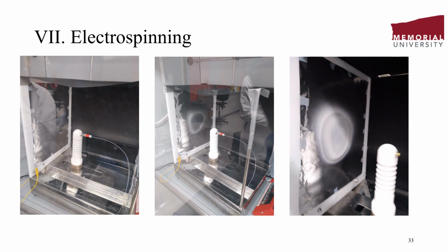The electrospinning process was started. Based on the first photo, the aluminum electrode shows that nothing has been sprayed. The second photo shows the initial stage where the needle has started throwing the nanofibers onto the aluminum screen. The experiment was run around 2 hours, and after 2 hours the last picture shows the nanofibers of PVDF solution. This was the end of the electrospinning process, where we obtained nanofibers using a PVDF solution as a result.